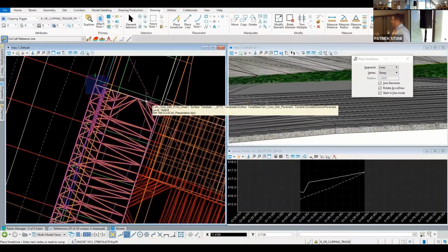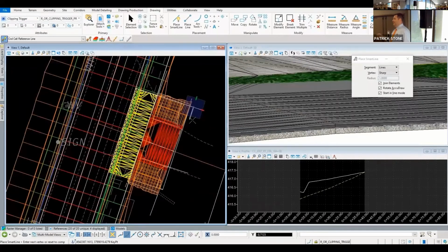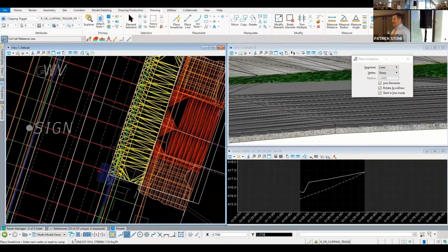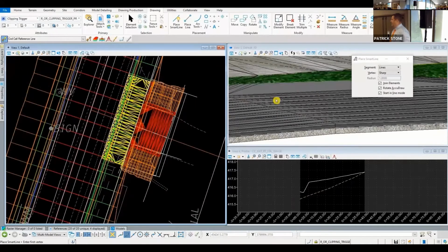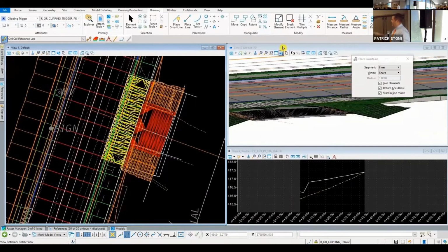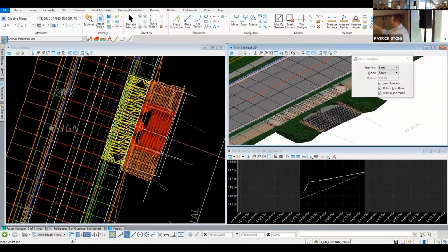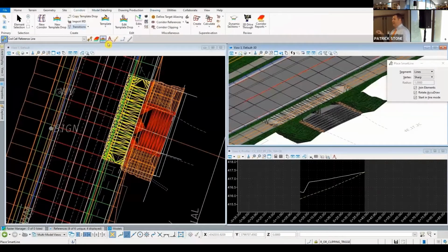Here I'm going through and flipping out my corridor. With urban, the way that Patrick showed you isn't going to work as well because we're needing those features for the curb and for the sidewalk to hand over to here. So we're drawing an element around there, and that's where you turn off your persist snaps. And what you can do is in your corridor, you've got that shape drawn around the area, and you can tell the corridor, hey, I want to clip based off of this element.